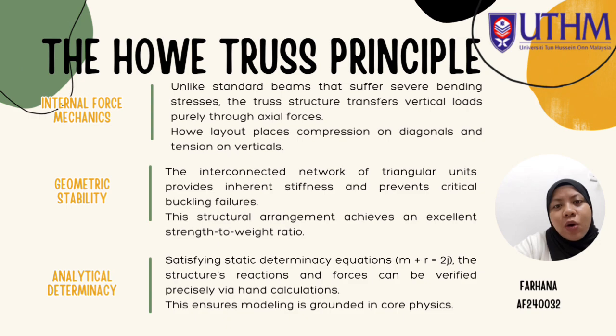So what makes the Howe layout unique is its specific arrangement. Under gravity loading, the diagonal members are placed in compression while the vertical members carry tension. This predictable load path is exactly what we aim to analyze.